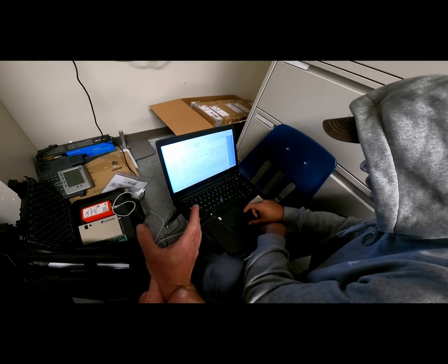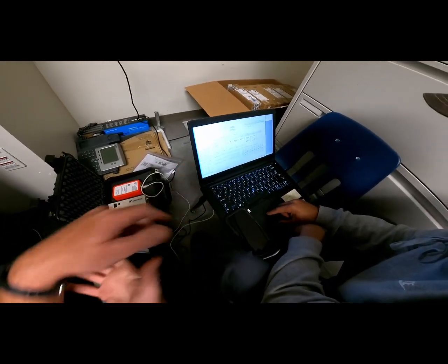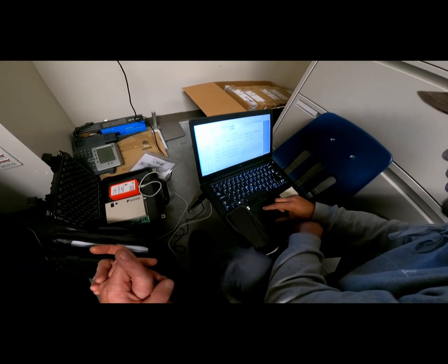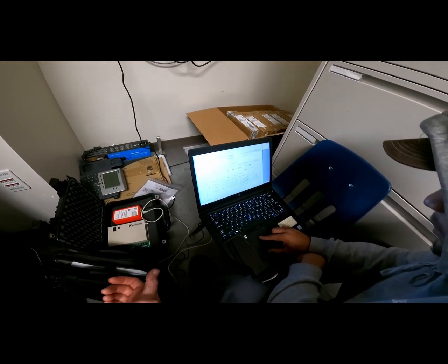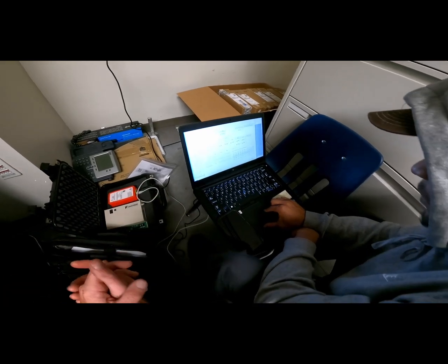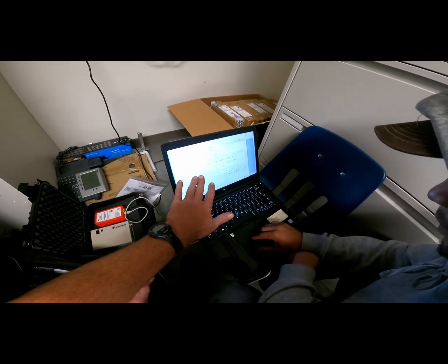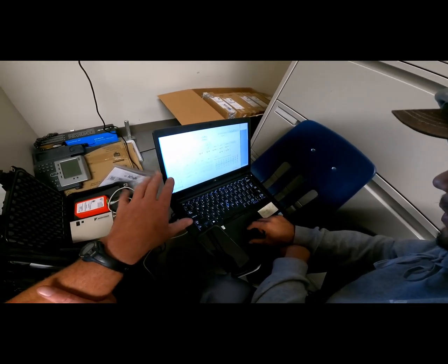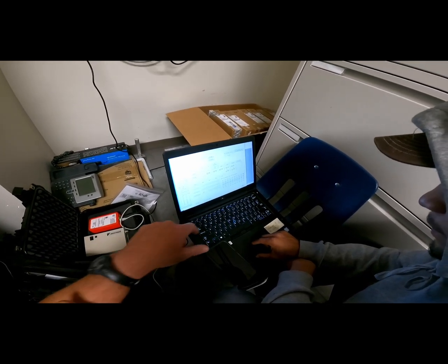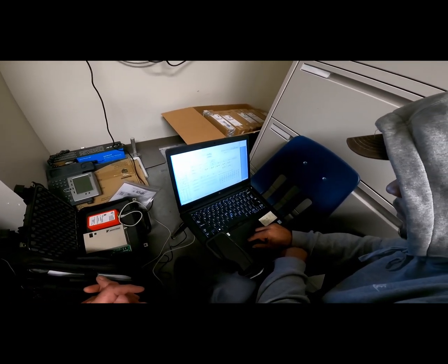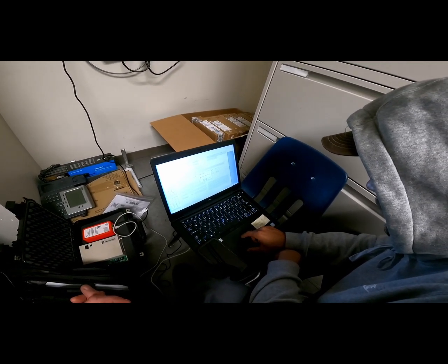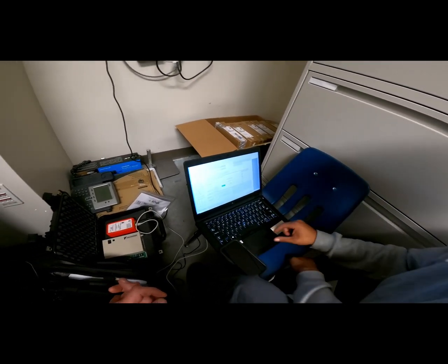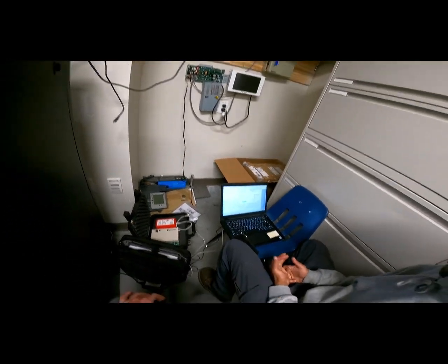Once you've got your addresses selected, you need to check the on-off button, and you need to put it in test run. Check the mode button, put it in cool. You don't need to worry about the temperature because it's just going to run full cooling. Click the fan, and it always needs to be on high. And then transmit. And it'll say batch operate indoor units 21 through 28. Now it's going to start going.